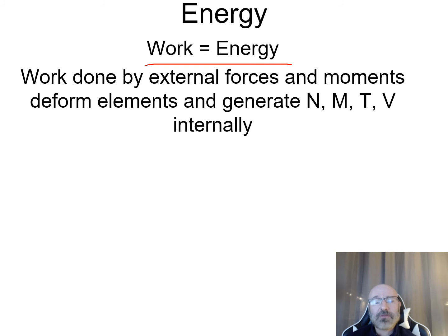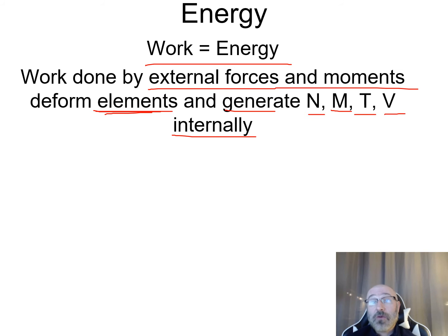So next thing I want to take a look at is energy. Now, as we've seen before in previous courses, our work is equal to energy. So we have this relationship that we've seen before, where we need to consider that work done by external forces and moments deform elements. So there are going to be deformed elements within whatever part we're looking at, and that's going to generate internally axial loads, moments, torques, and shear forces, all internal to our part on those elements.